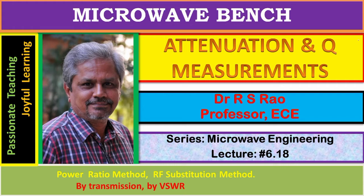Presence of resistance, presence of capacitance, indicates the non-ideal nature of the coil. Their amounts give certain information regarding the distance of a practical coil from an ideal coil. How near a coil is to an ideal one, or how far a practical coil is from an ideal one, is measured by one parameter. It is Q factor, quality factor.